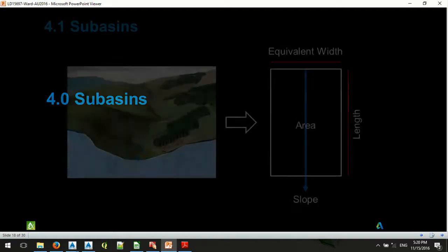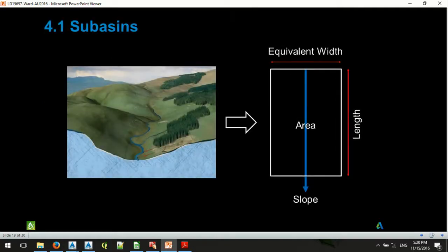for compositing stuff together. Okay, so if you think back to the open channels example, the way that SWMM and SSA sees a sub-basin is that all that lovely complexity of the landscape gets abstracted and turned into a rectangle that has a length, a width, and area, and is perfectly bisected by a flow path down the center. And the problem is, if your design is not a rectangle that's perfectly bisected by a flow path down the center, how do you communicate that to SSA?